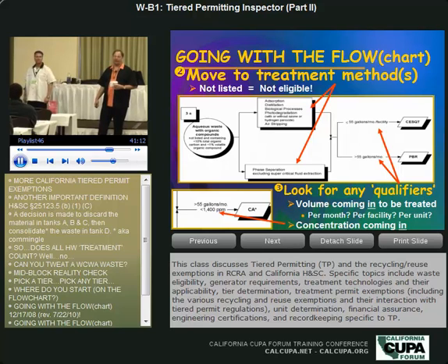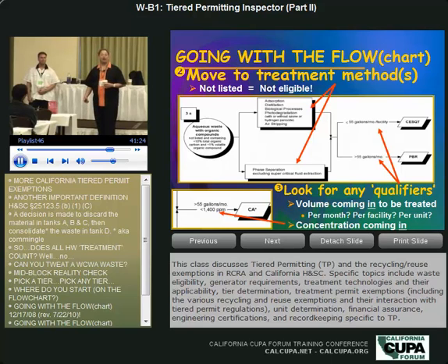Same thing. If they come in with their application at 1,350, 1,300 ppm, how representative is that? Or they come in and say, look, we've got 1,800 ppm. What that tells me is that facility should do a lot more pollution prevention and source reduction up front. Maybe there's something they can do early in the process: raw material change, process substitution, to knock that concentration down, to get them into a lower tier.